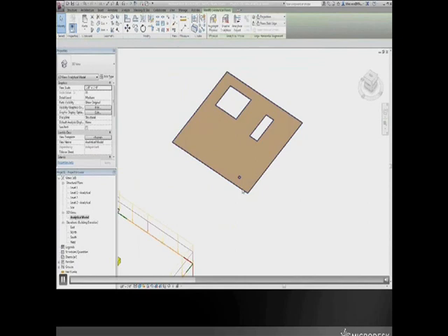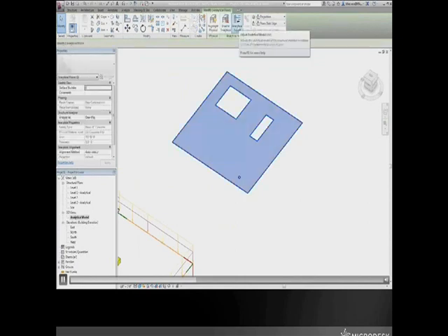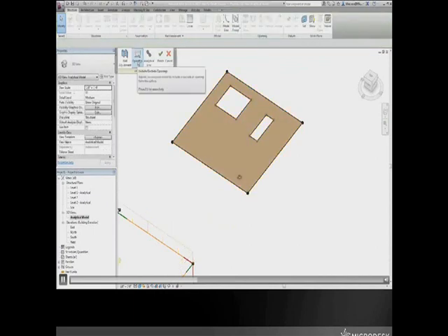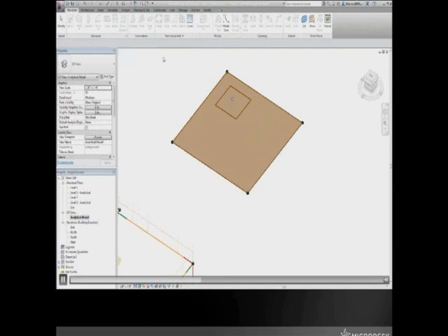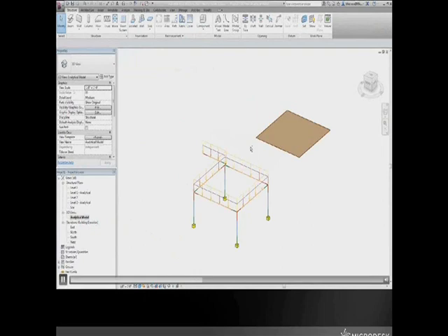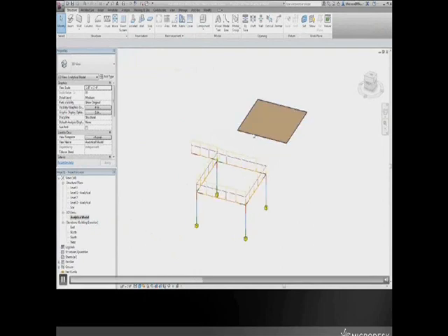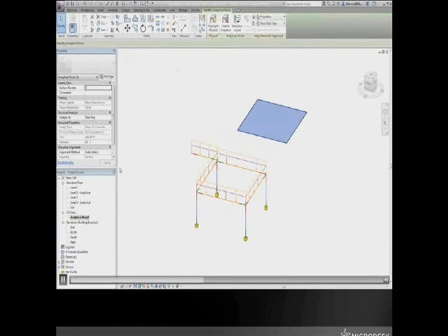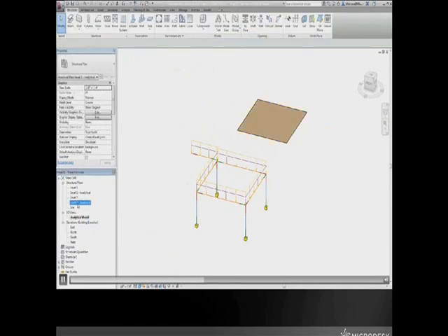go to Analytical Adjust, and go to our Openings button here. And you'll see that there's a little checkbox that comes up. And if I uncheck that, the holes will go away. They may physically be there in the Revit model, but they are not going to be used for analysis in an analytical model. So if this was sent out to the cloud or to Revit Structure, it wouldn't analyze the holes. So I'm going to go back and create a couple more shaft openings.